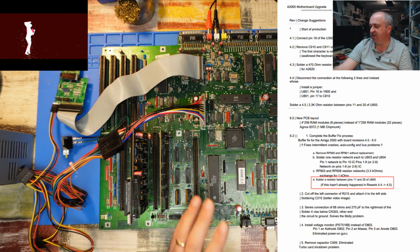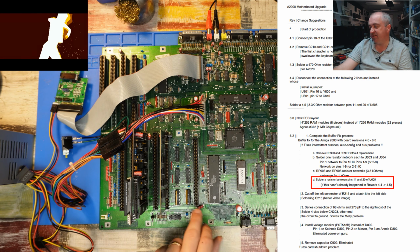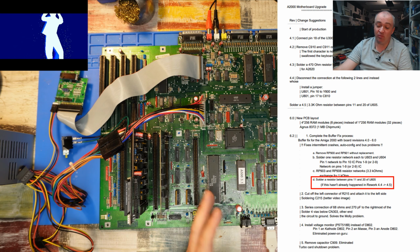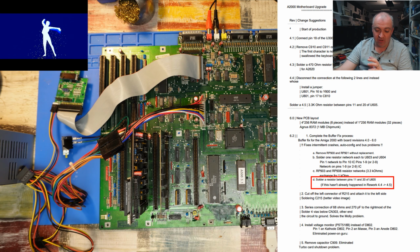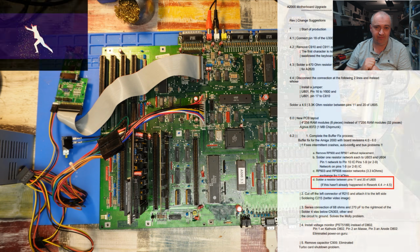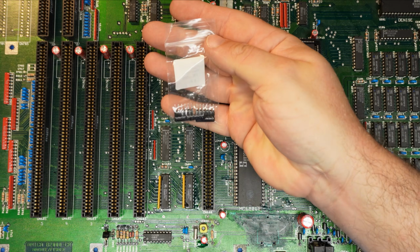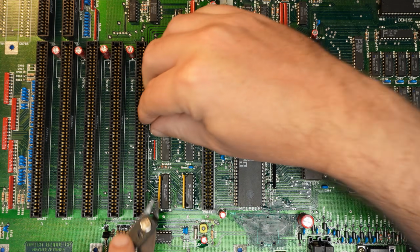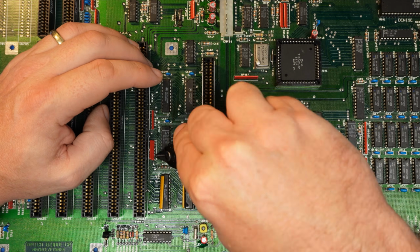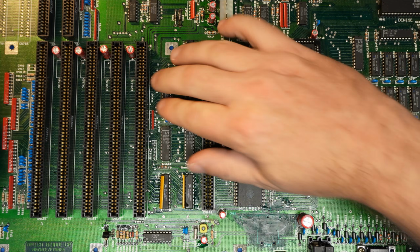Yeah, it's listed in this engineering guide from Commodore, but it's not on the 6.2 schematics, and it doesn't seem to be on any pictures of 6.2 boards, so I'm not going to bother with it. All we're going to do next is swap out those two resistor packs. Okay, so these two out, and we're replacing them with these. Just going to try and do the same thing again though, and we'll just cut these out. And then I'll just go along and desolder all those legs.